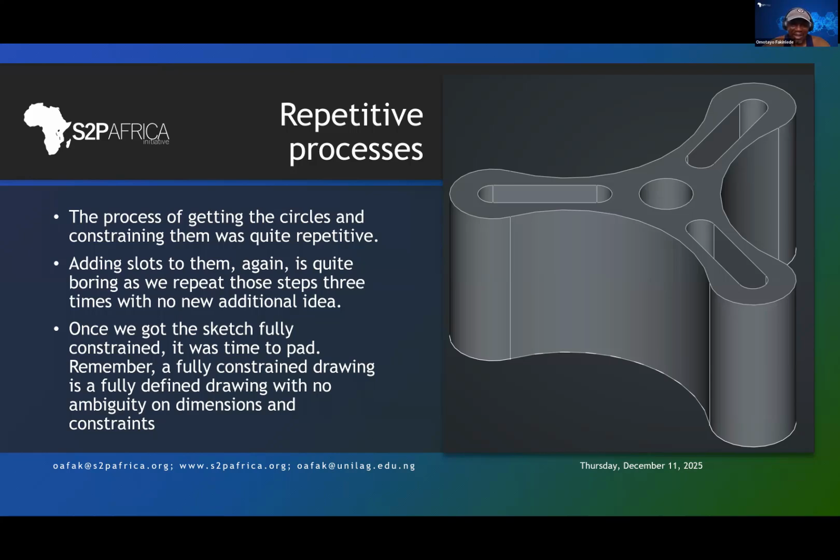You need your drawings to be fully defined for simulation, because in simulation, all the dimensions will be exact and there will be no ambiguity. When something still has degrees of freedom, it has the freedom to choose the wrong thing, to choose another thing. So you remove the degrees of variety. Sometimes your system is over constrained. I'll show you an example of over constraining shortly. And so let us see how it goes, adding slots and some other things. Let us move on here.